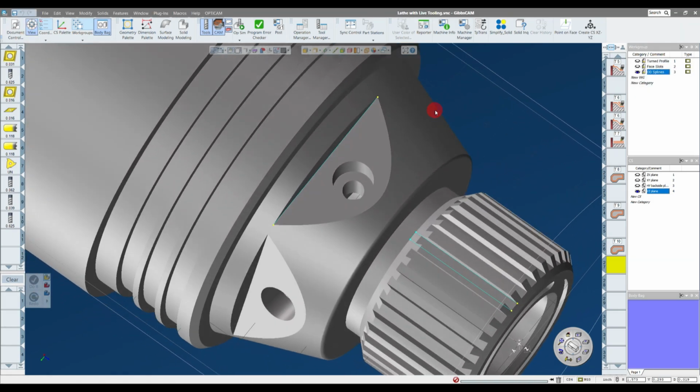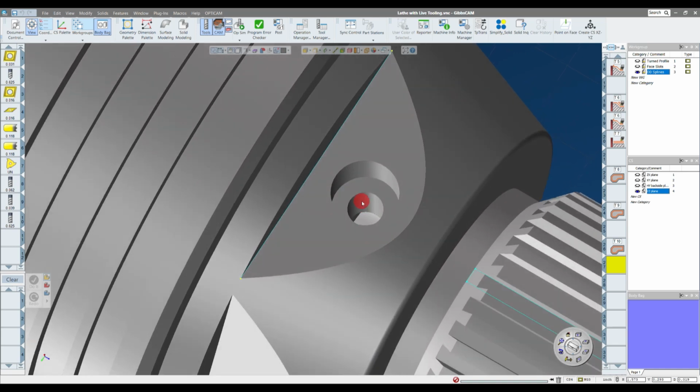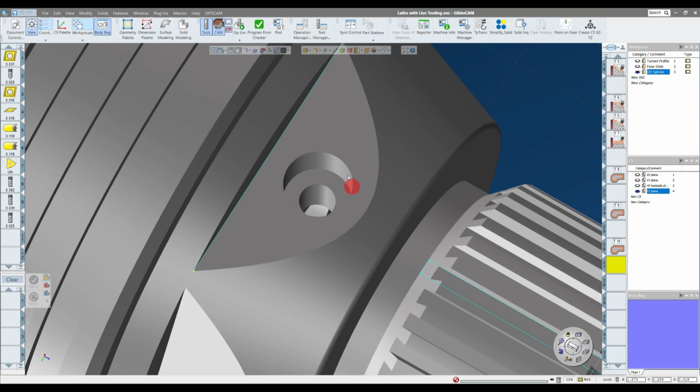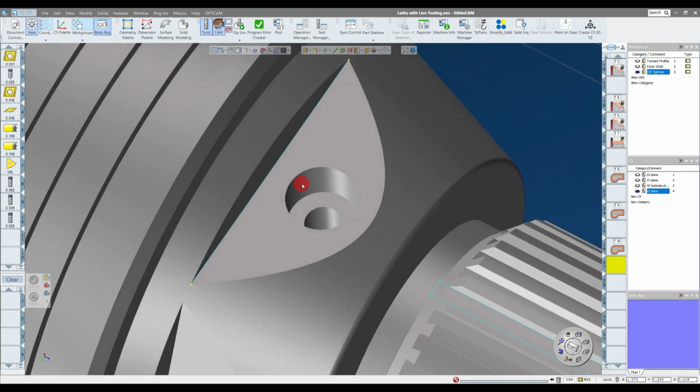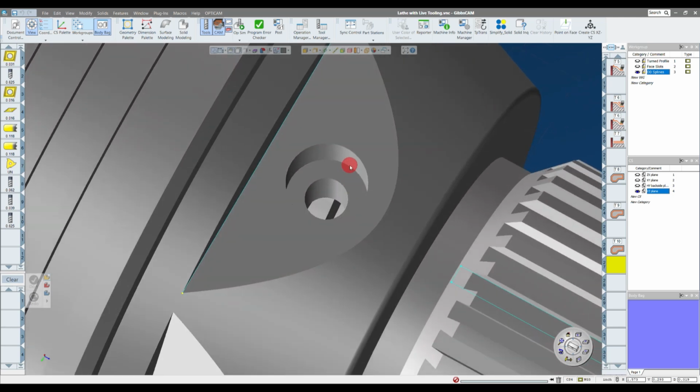All right, so what I'll need to know is the diameter of the counterbore and the diameter of the through hole. Now I do need a counterbore. If I'm going to helically interpolate this with an end mill to do the counterbore, I'm not going to plunge it. I'm going to use a smaller end mill and do a helical interpolation. I need to pull that geometry for that counterbore.